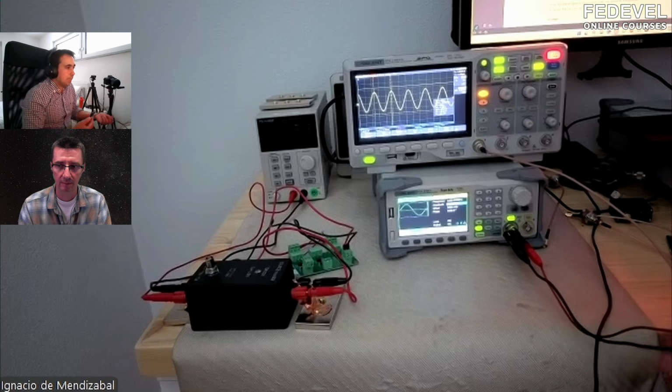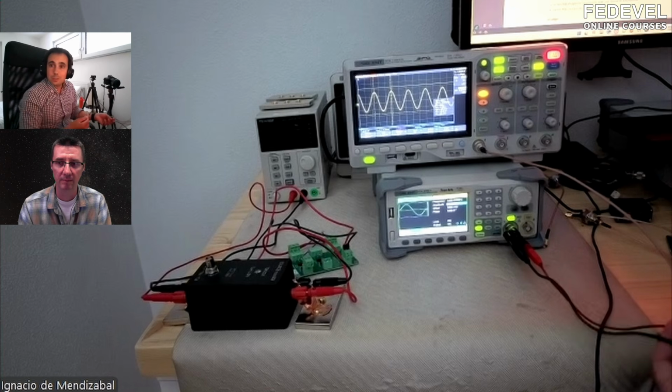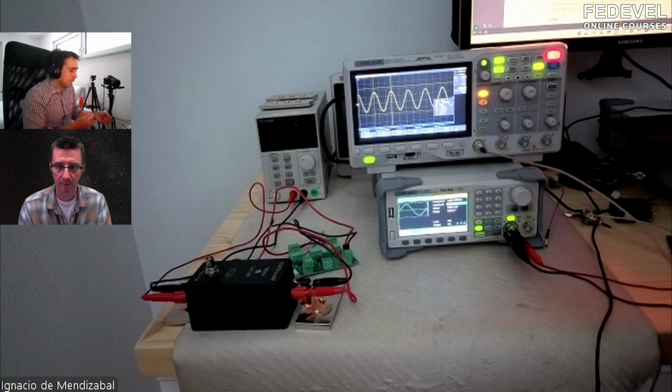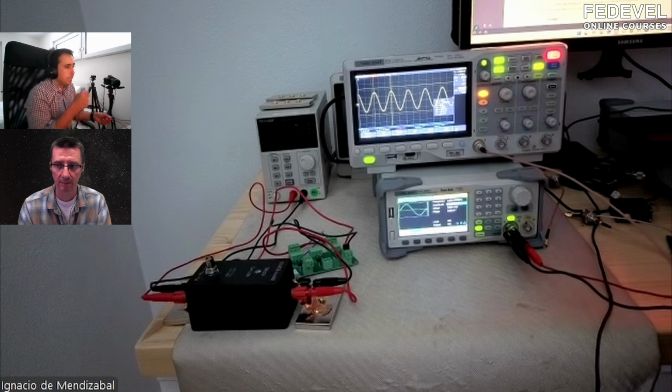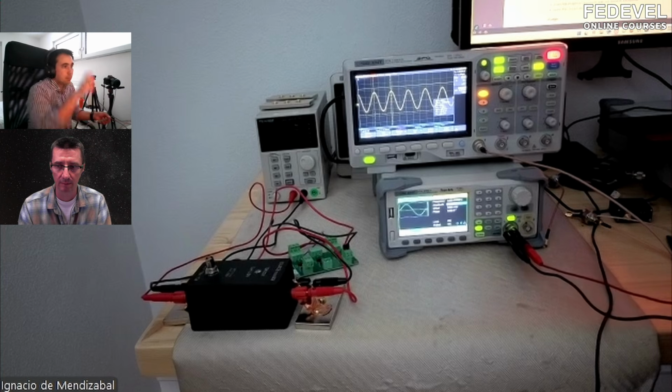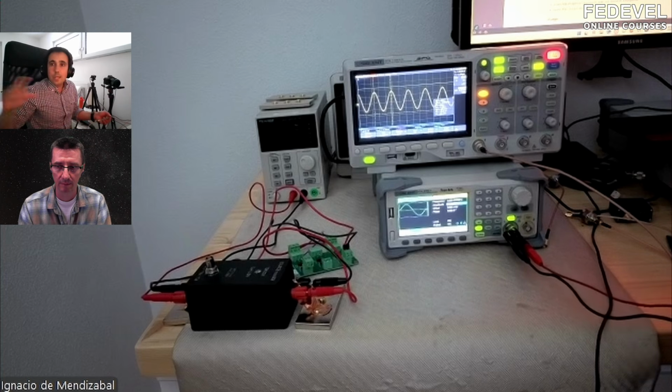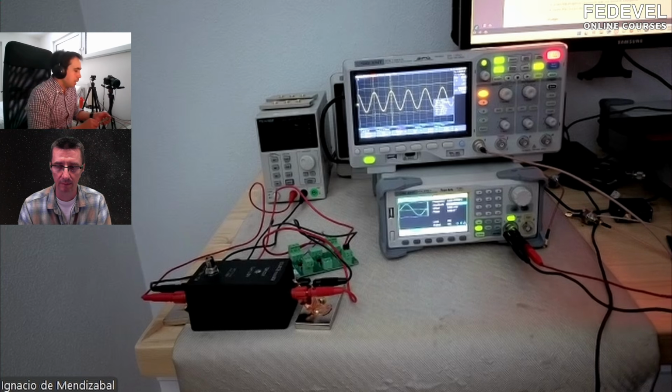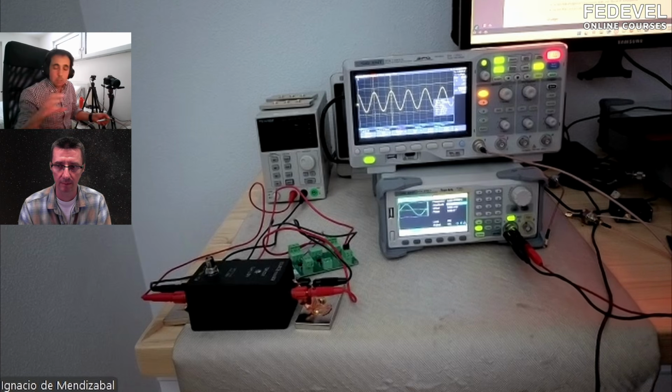In the end, a near field probe, a magnetic probe, is a transformer. We inject a signal that is coupled and generates a magnetic field, and then we capture that magnetic field. In between, we lose part of the signal, which has the inconvenience of losing amplitude.